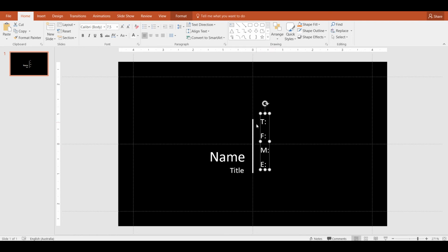I'm going to just change the size of these. To change the size of shapes and boxes, what you have to do is just rest the mouse over and click one of these dots. Keep left clicking so you can move them up or down. To select both of them, just keep left clicking on an empty space area and fill this rectangle. Then go down so they're in the middle, and do the same for the name and text. You can also select the box, press Shift and click another box, so both of them are selected.